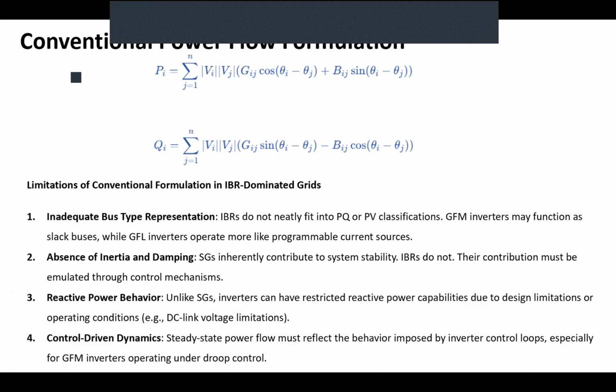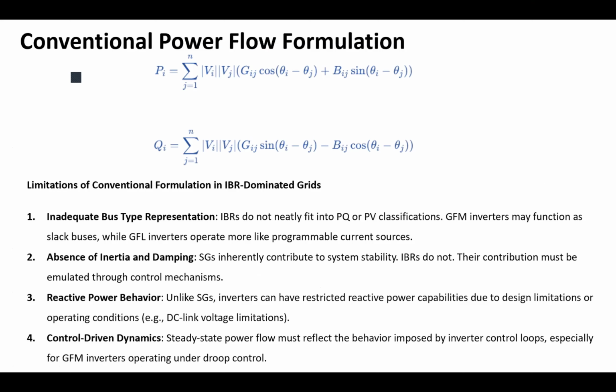In the previous session, we already saw the equations of the power flow analysis. We wanted to calculate the active power and reactive power that is transferred between each two nodes in our system. We ran a KCL, and after all those thoughts and processes, we reached two equations: one for active power based on the characteristics of the two nodes we want to analyze, and another for the reactive power.